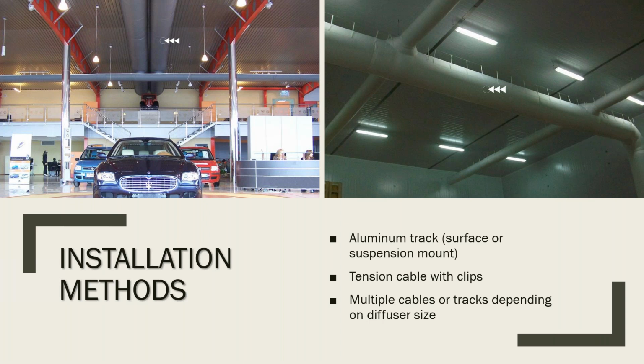If you can imagine, that duct is big enough for a person to walk through. So that would require a suspension method that can hold that full amount of fabric. With that, you will probably go with a 3-point cable suspension. But then there's also track suspension. Track suspension can be either surface mounted, or it can be hung below the ceiling with cable drops.